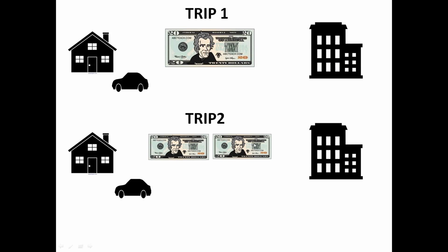So that's kind of what a poor power factor is doing to the system. It is making the generating plant or the generating utility spend extra money and fuel to do the same work.